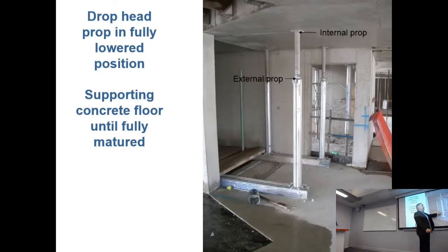So we've got beams and timber holding up the concrete. They drop that and leave the props in place, and you've got to leave the props in place until the concrete has reached sufficient strength to hold itself. And what you'll find is that they're going to be building another floor on top, so the weight of the floor is being supported by these props, and if you put another floor on top, you've got to make sure it is strong enough before you remove all of these supports.